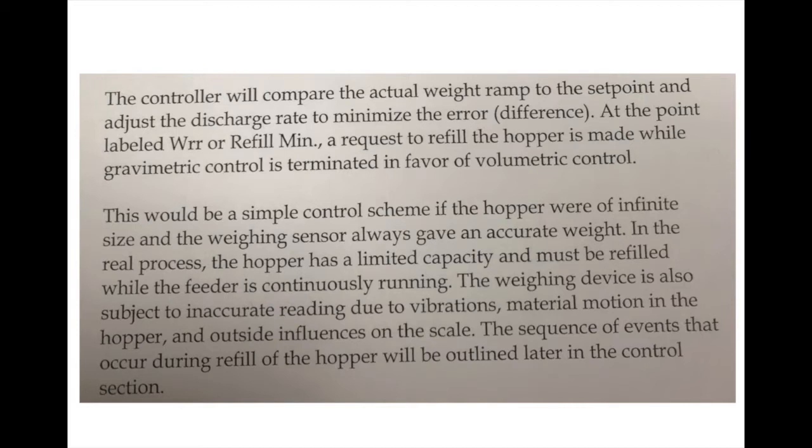And the reason why it has to go into volumetric mode is because during the refill, you're not getting a loss in weight, you're actually getting a gain in weight. You're not actually able to calculate the set point.